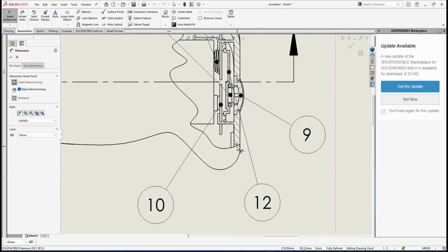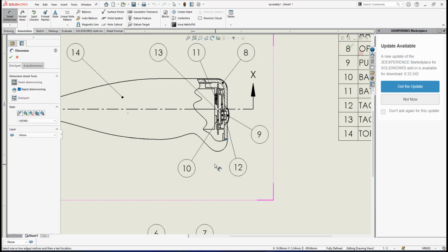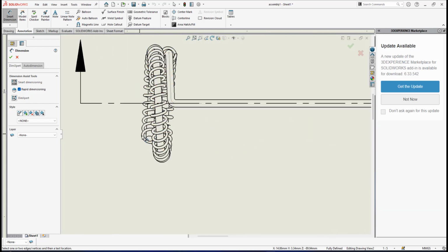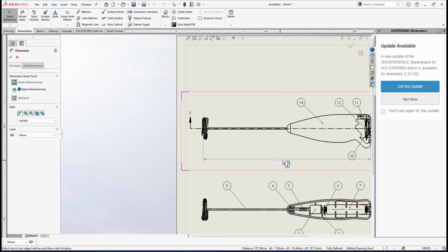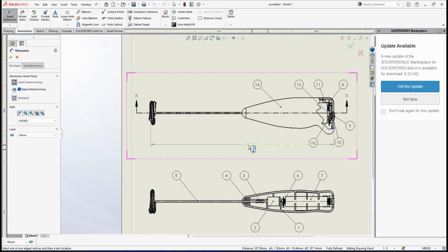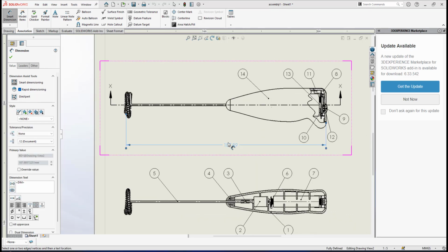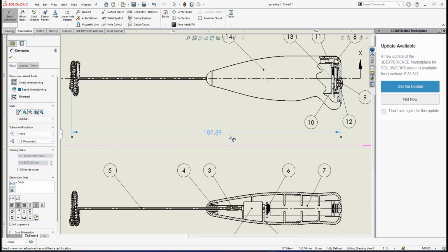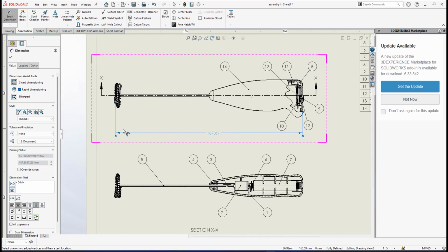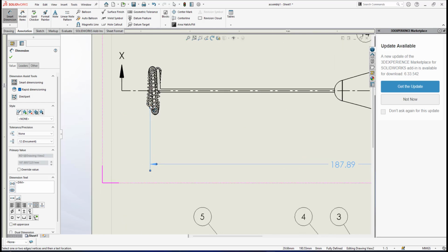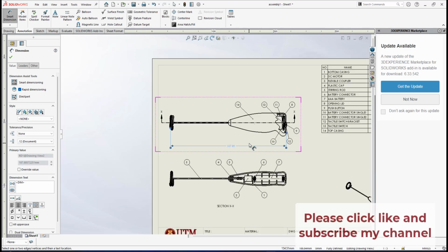Make sure that I can snap at one point here and up until the other. Sometimes it cannot point to this curve, but as long as I can, we have a dimension here showing the overall length of this frother. I have this dimension to 2 decimal points, to show the length of the frother up until the cross section of that helical rod.